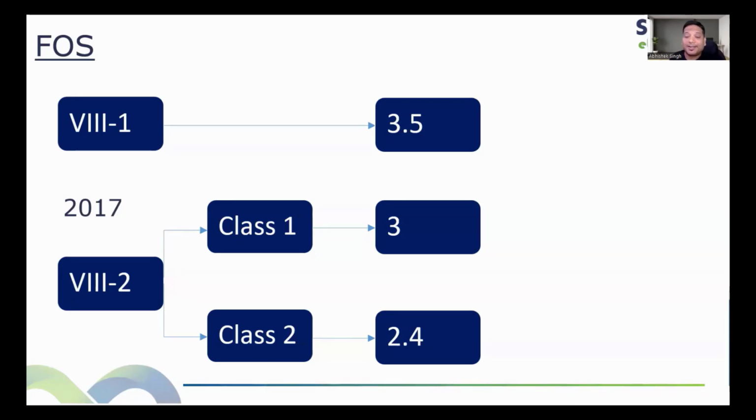Now, this is very interesting. For Class 2, do you need to perform FEA? The answer is, for Class 2, you don't need to follow design by analysis or Part 5. Class 2 also you can do as per Part 4.